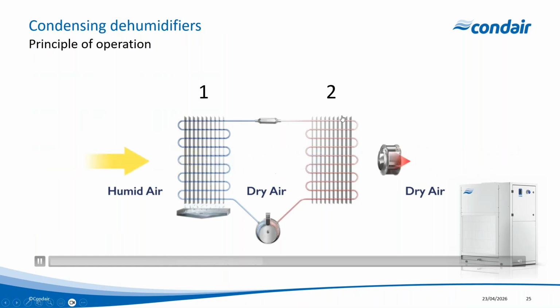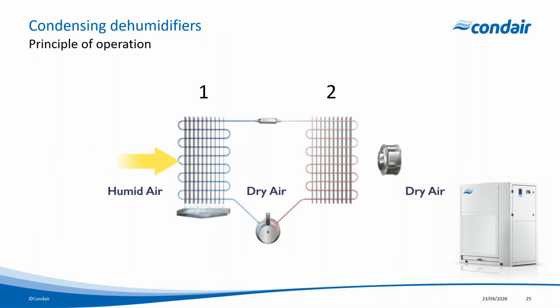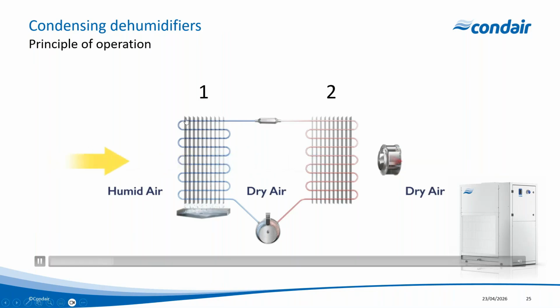That goes through the condenser, but at the end of the condenser, we have a pressure changing device where, as we've condensed the refrigerant back into a liquid, as the liquid goes through the pressure reducing valve, or typically a thermal expansion valve, we then change the pressure so the refrigerant will boil at a much lower temperature.